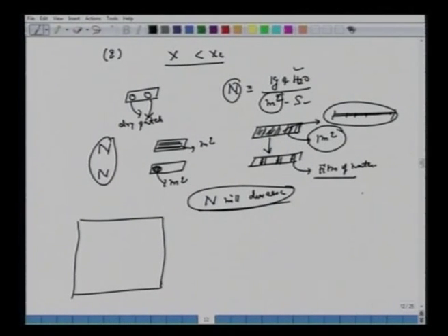So if you do this experiment, you have the solid suspended and measure how the moisture content decreases. Then what you will expect is that here also you will have several regions. There will be one region where x will decrease linearly, then it will slow down, then it will slow down further. So next time when we meet, we will mark these points A, B, C, D here. We will call it constant rate because x changes linearly.